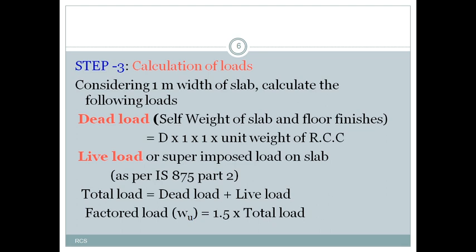Overall depth is equal to effective depth plus effective cover. From that we can calculate the overall depth. Then the problem will provide you a design live load, which can also be called a superimposed load on the slab. This conforms to IS 875 Part 2.